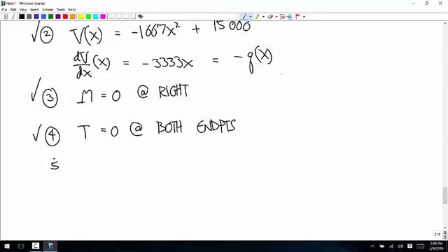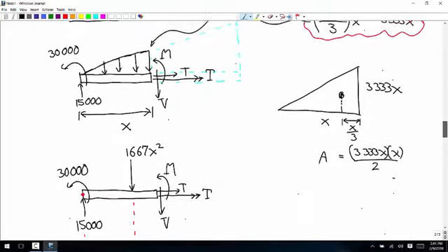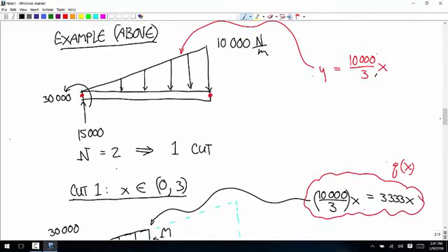And then shear force. Where would we expect there to be a non-zero shear force on this? For x equals 0, we'd expect that shear force to be non-zero because we have this vertical point force. There's no vertical point force here. There's a distributed load, but remember that distributed load applies infinitesimal force at that point. So we expect V equals 0 there, not 0 here.